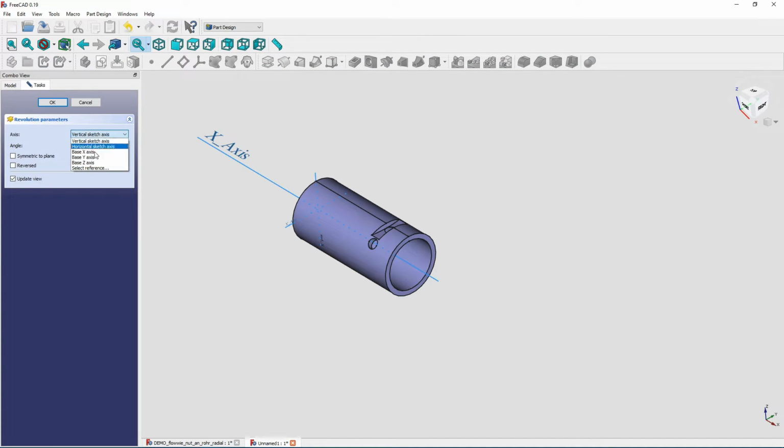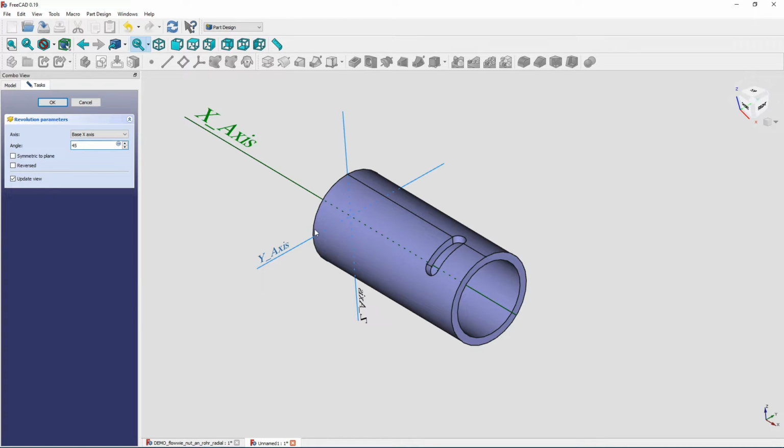The groove goes around. Let's select the reference again, the x-axis here, not 360 degrees, because in this case we will lose our pipe. We don't want this to happen. So we could say 45 millimeters, but if we change the polar pattern, then this would not follow. So we also have to define it here as an expression, and we just have to say polar pattern dot angle. So the angle of my groove here will always follow the angle of my polar pattern.